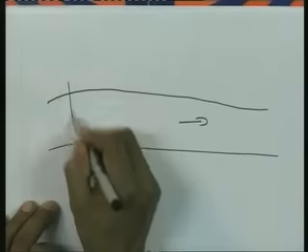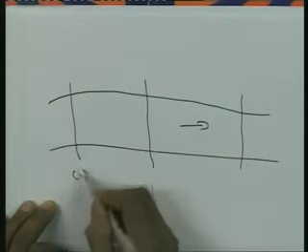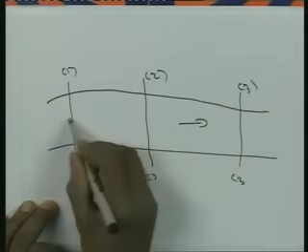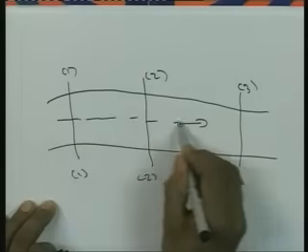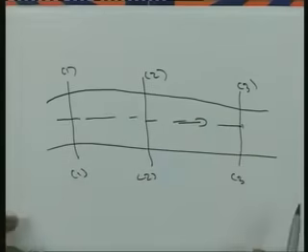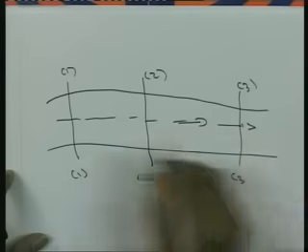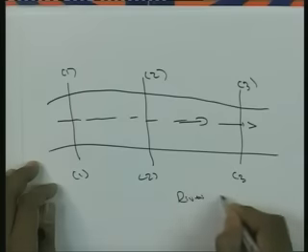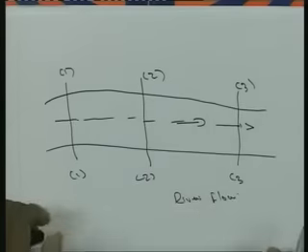And the same river flow we can sometimes consider as 1 dimensional flow. For example, say the river is flowing like this. When we are dealing with what is happening from one section to another, say here 1-1, 2-2, 3-3, from section 1 to section 2 and section 3, obviously the fluid flow is 3 dimensional in nature, but what is happening with respect to the longitudinal direction is what we consider as far as this river flow is concerned. So, in this case we can consider the fluid flow as 1 dimension.